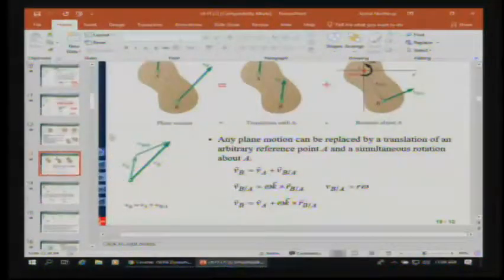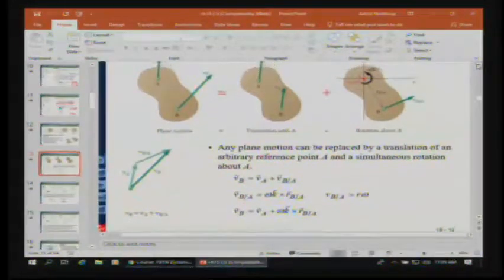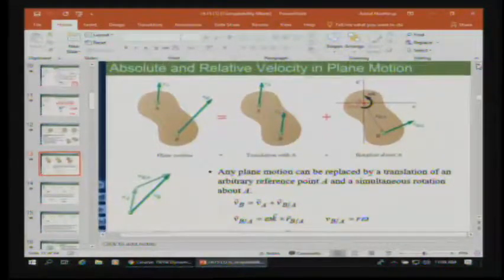All right, so when we start breaking this down into vectors, we have to remember that since we're talking about a rotation of one point with respect to another point, we're talking about a relative velocity. So we have an absolute velocity, or a fixed reference frame velocity, of one point, and then the relative velocity, which is the rotation of the second point with respect to the first.